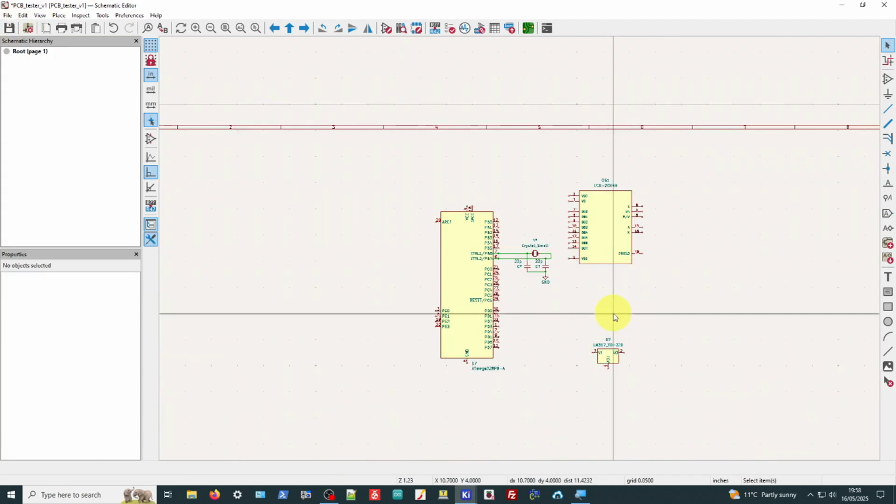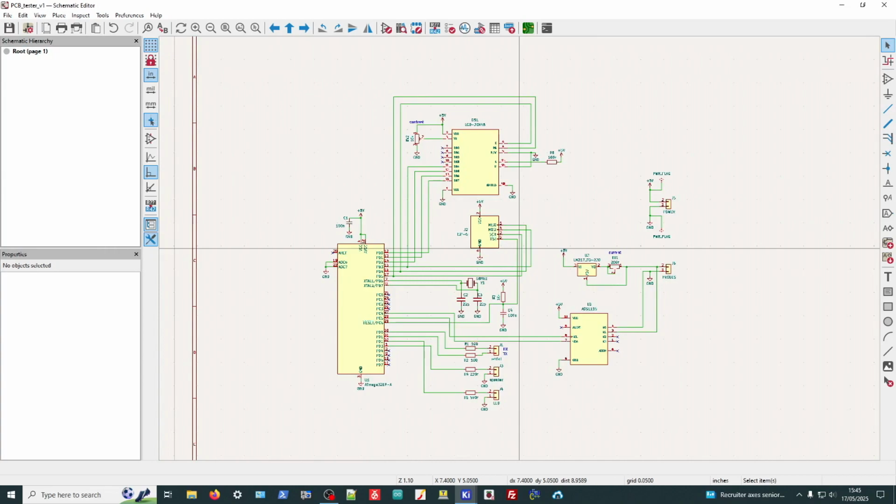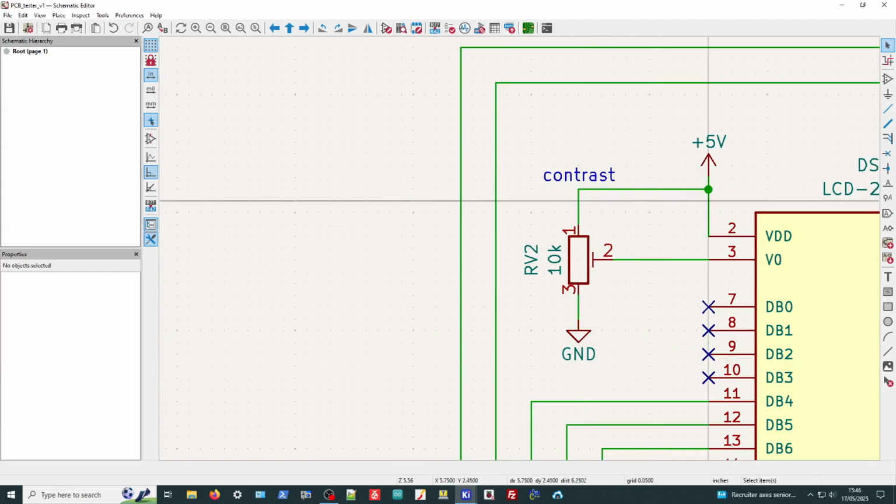Yeah. So what I'm going to do now is keep going. We'll do a cut, and I'll add more components, and we'll come back with a bit more circuit diagram. So as you can see, we've added some extra components. So we've got a little preset resistor here for the contrast. This basically is just an adjustment between ground, or 0 if you like, and plus 5 volts.